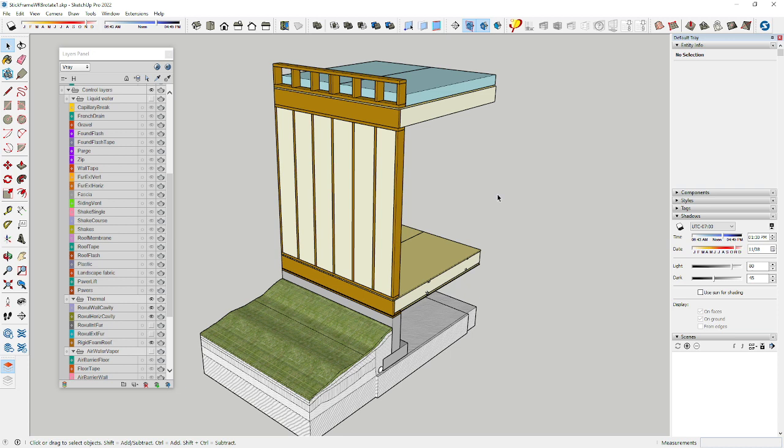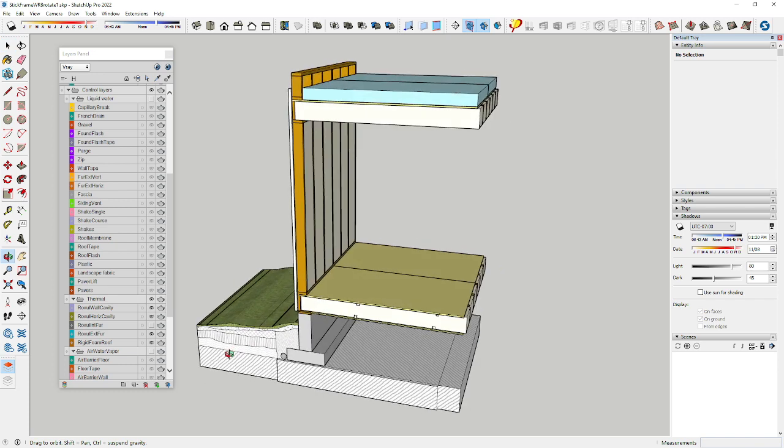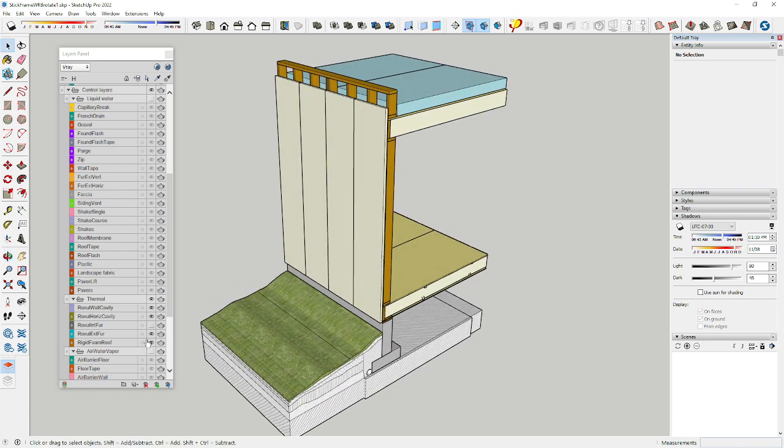In the case that we just did, we said, okay, we're going to make this 10%, this 90%, and we're just going to add up the paths for each of those zones. That can work, but it only really works for sure if you have insulation on the outside. So this insulation on the outside of our cavity allows us not to think of that cavity as a thermal bridge, or those studs as a thermal bridge. This is much worse with metal studs. Metal studs really suck heat through them, so they really degrade the insulation value.